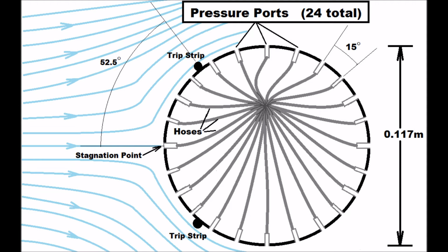The RPM was then increased to 600, where we also collected 3 data sets after a settling period. Each data set we had consists of 24 static pressure readings equally distributed around the cylinder, with the first being the stagnation pressure.